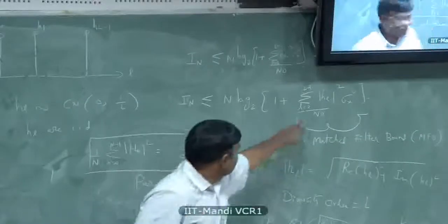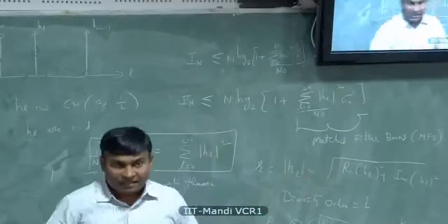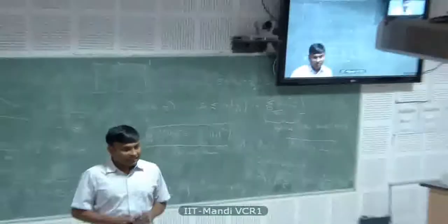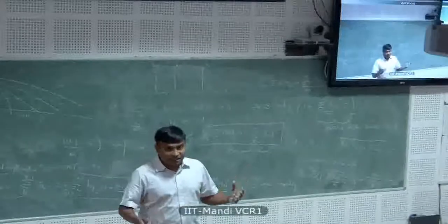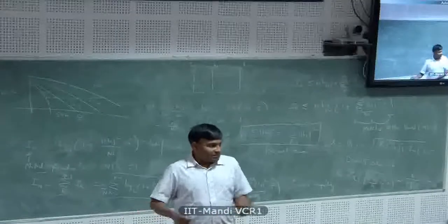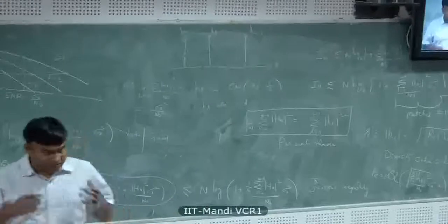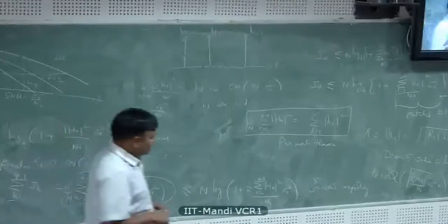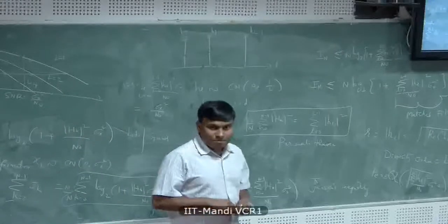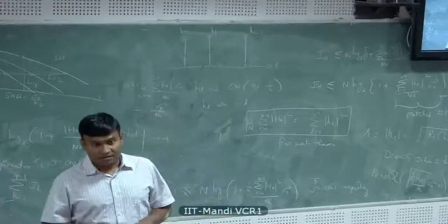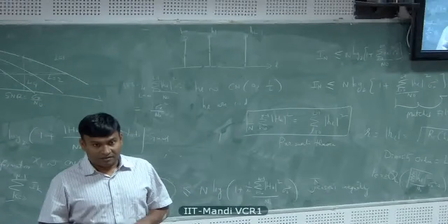If you have 2 antennas, 0 and 1, then I have second order diversity using 2 receive antennas. If I have 4 receive antennas, I have fourth order diversity, because the channel is giving me a nearly flat channel, I mean, nearly flat impulse, single tap with flat frequency response. But in GSM mobile phones, the length between the two antennas is quite large.